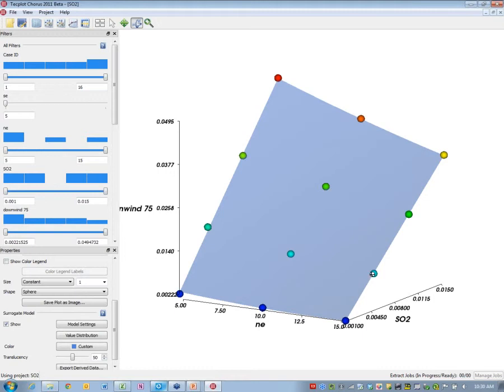The other thing here, just to describe the surrogate model a little better, to get any information about what's happening between the points, you really need to have some sort of a model. It could be just a linear model, but in this case, I believe what we've actually done is, is this the response surface? Yeah, it's quadratic. So this is a quadratic response surface.